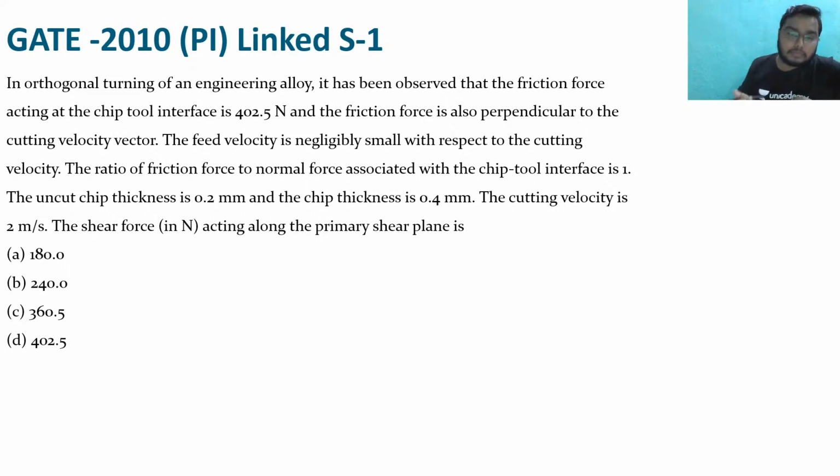For those who are not understanding, I am just telling you, this is orthogonal turning. Clear? It has been observed that the friction force acting at the chip tool interface is 402.5 Newton, so F is 402.5 Newton. And the friction force is also perpendicular to the cutting velocity vector.